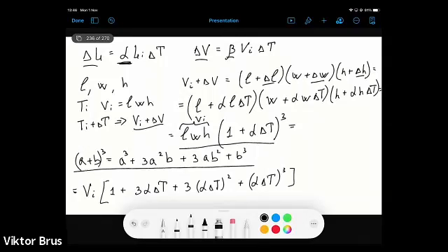Now we need to recall, as we mentioned at the beginning, that thermal expansion is quite small, and that's why it's difficult to measure thermal expansion with high accuracy. So in a small temperature range, when delta T is not very large, the product of alpha times delta T should be smaller than unity, because alpha is a very small coefficient.